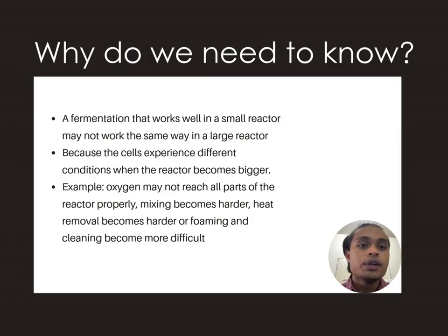Okay, so why do we need to learn this? Well, a fermentation that works well in a small reactor may not work the same way in a large reactor. And that is because the cell experience different conditions when the reactor becomes bigger. For example, oxygen may not reach all parts of the reactor properly, mixing becomes harder, heat removal becomes harder, or foaming and cleaning becomes more difficult.